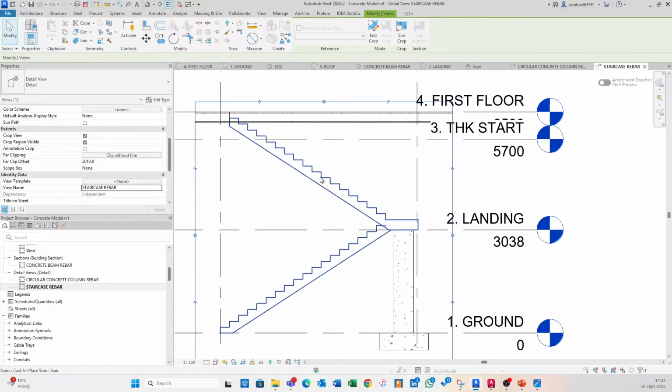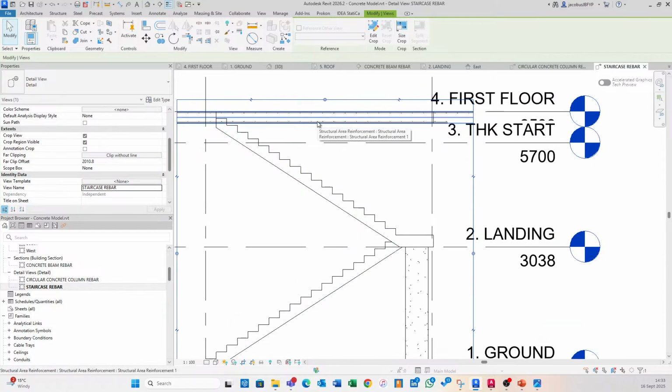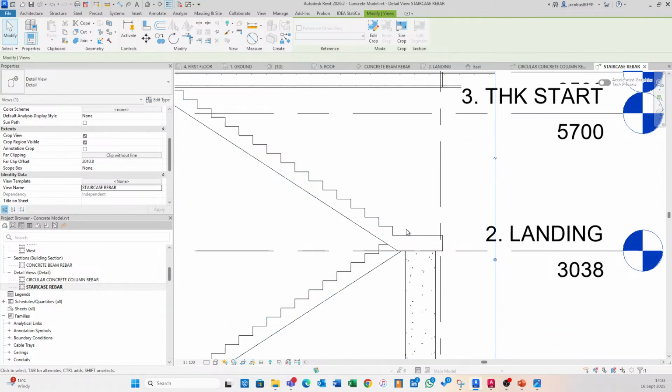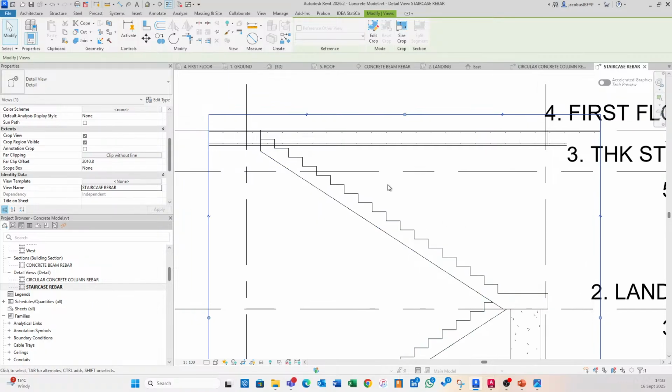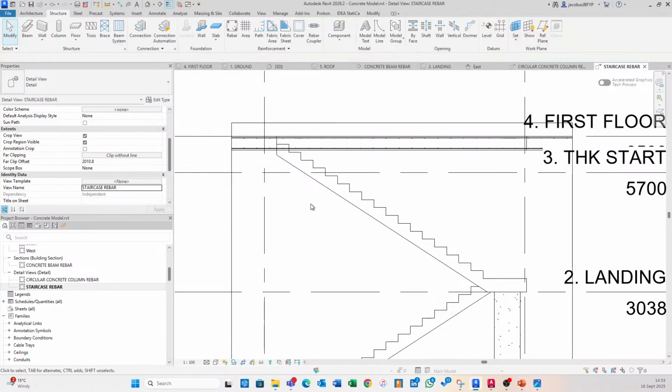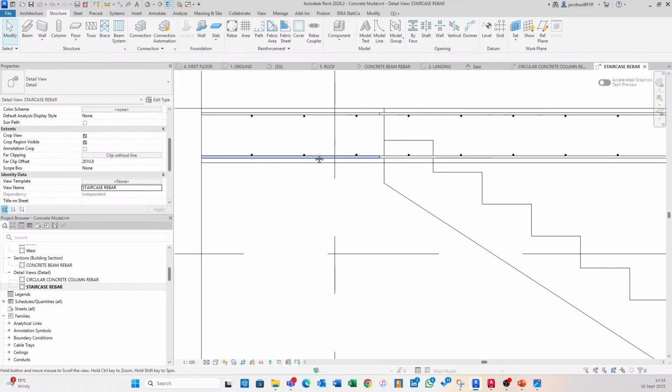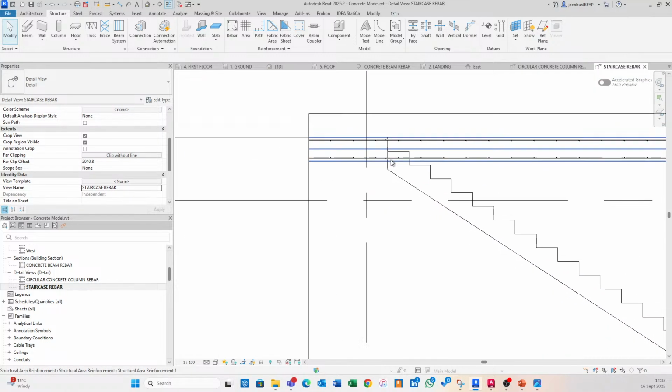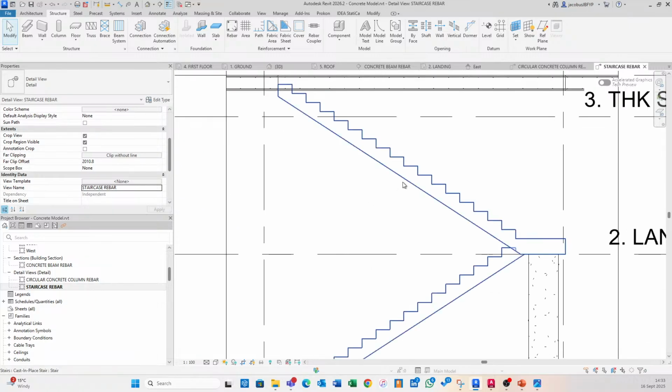So this will work a little bit better than some scenarios just because the landing is fortunately seen as a part of the staircase. But you'll notice something interesting when it gets to your tie-ins. So when we have to actually tie in to this rebar at the top, it can get a bit tricky because you've got two hosts.